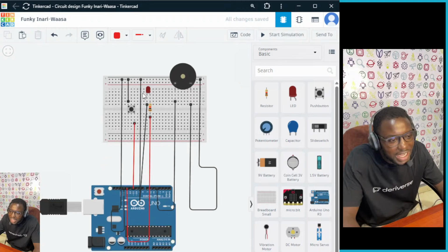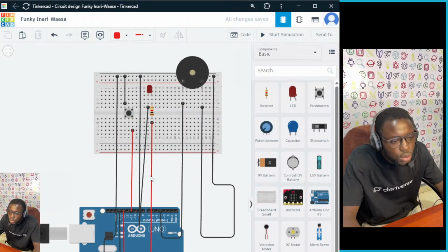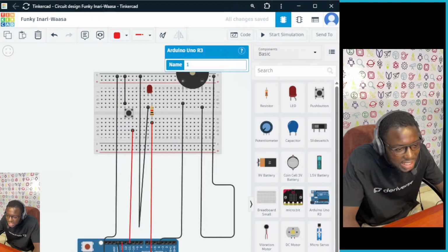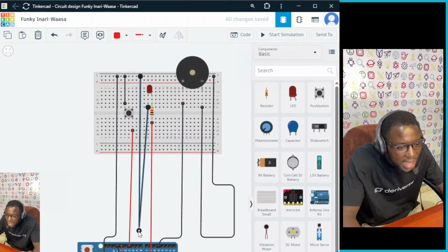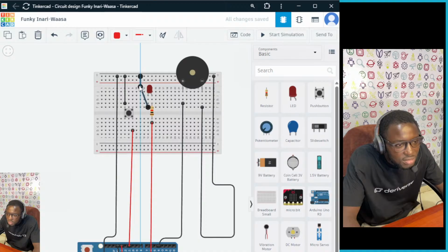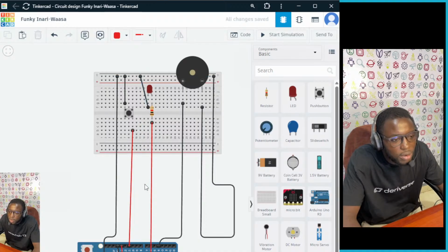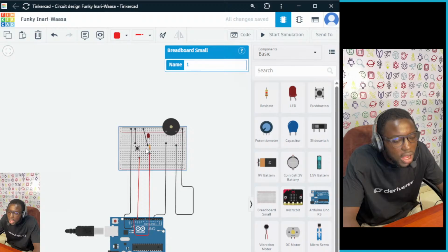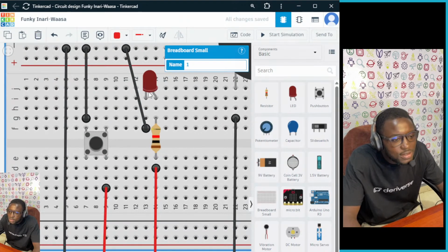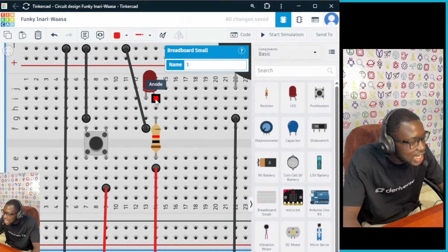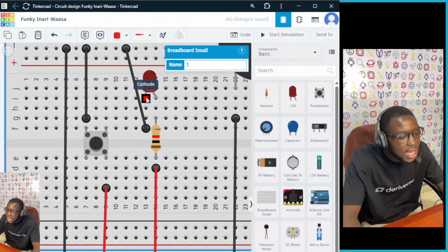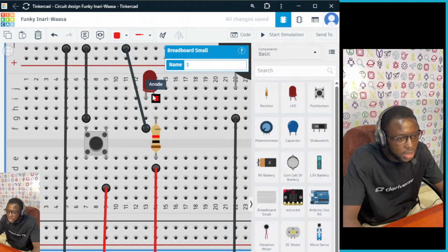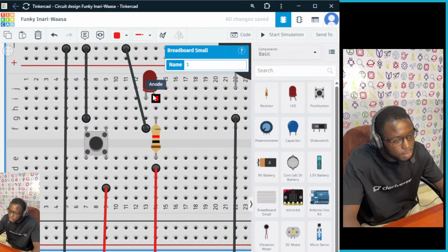I'm going to focus on my second component, which is my LED, and look deep into how my LED is built. One terminal of the LED hasn't been connected. I can see right away my LED is connected from here to this side. So I'm going to make that connection. So simple. And then don't forget about the LED: the LED has two terminals, the positive and the negative terminal. So I'm going to start with the cathode, which is the negative terminal, and make all my connections. And when I'm done, I go to the anode connection, which is my positive terminal, and make all my connections.